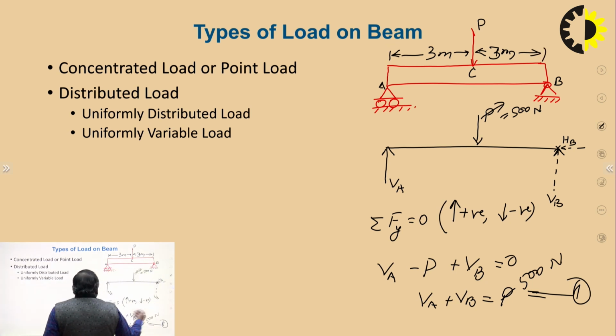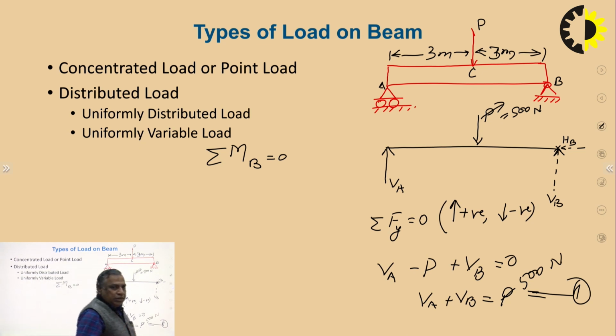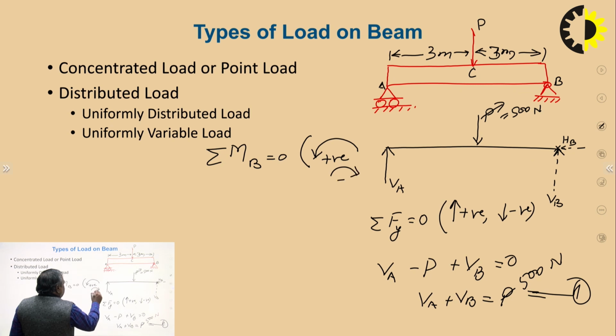Then I will use another equation, summation MB is equal to 0. The sign convention for moment: anticlockwise moment I will consider positive, and clockwise moment negative.